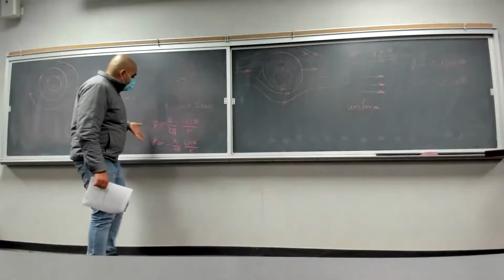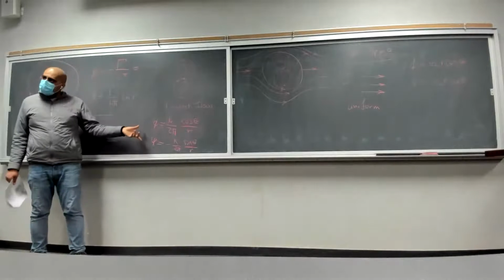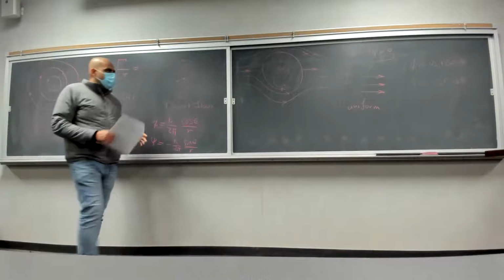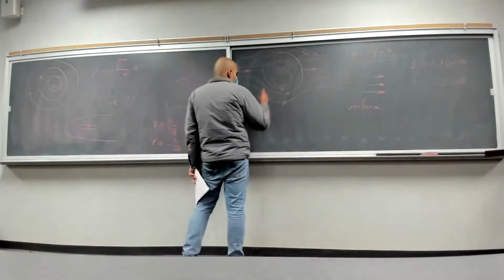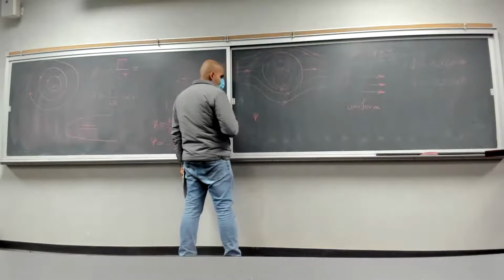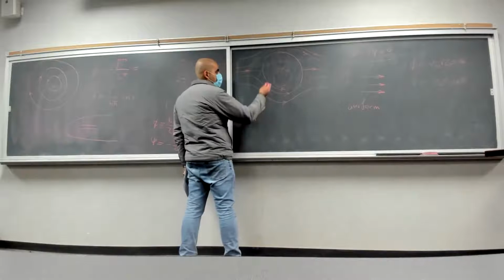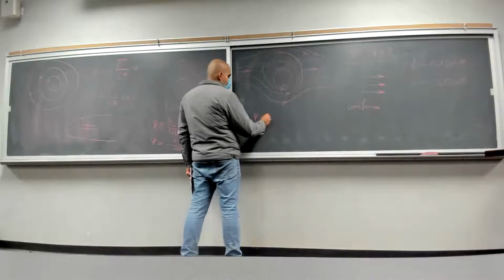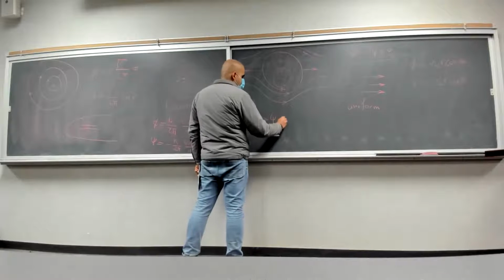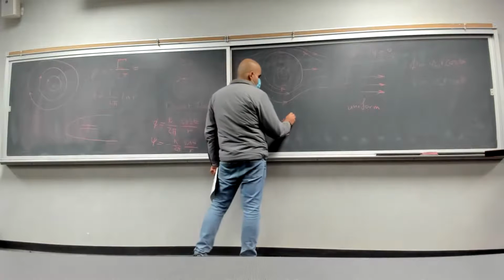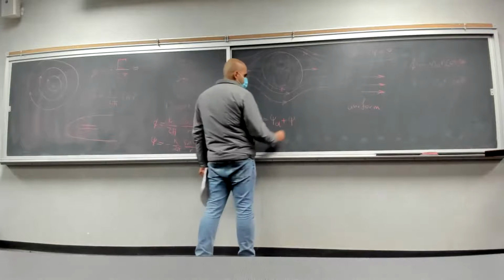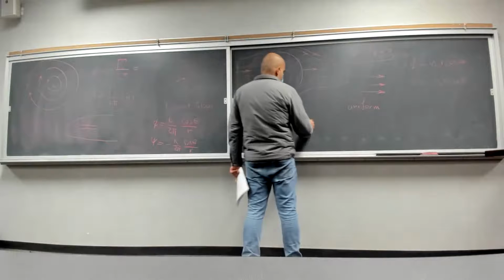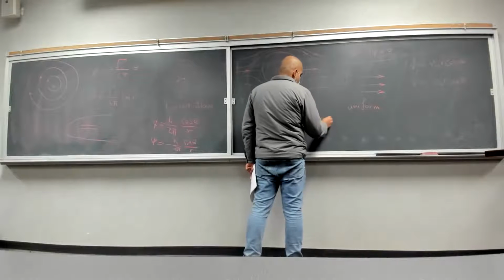So we also have the psi and phi for the doublet flow. To get the velocity profile here, we can find the psi of this type of flow. Let's call it the cylinder flow. Psi of C is going to be equal to psi of doublet plus psi of uniform flow. Psi of uniform flow is V infinity r sine of theta.